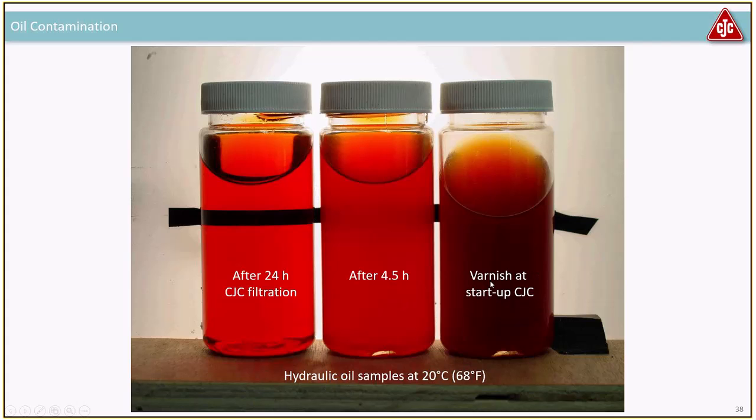This is why you can do something like that. Here, a startup of a hydraulic system, you cannot see through the bottle, the tape on the wall. After 4.5 hours, you start to see it, and after 24 hours, you have removed the particles and the varnish from that. And that is only because you're using this depth media that can take the varnish and the particles out.